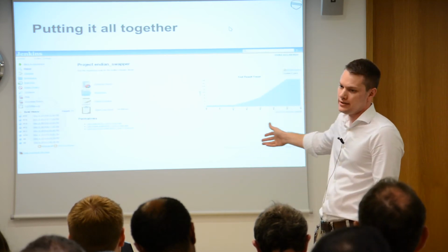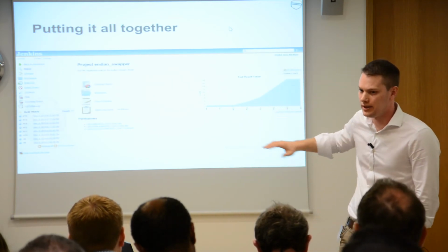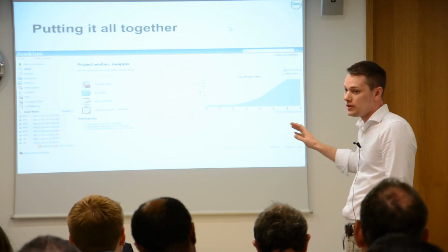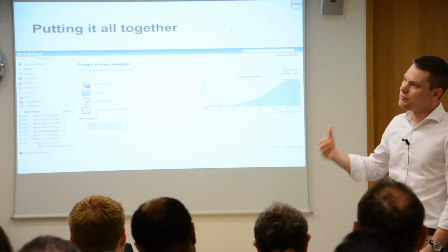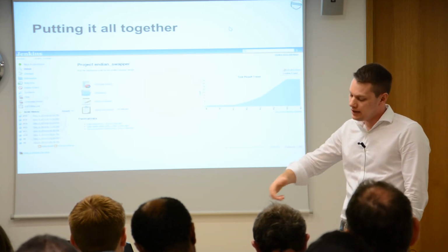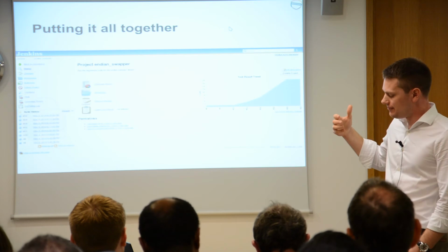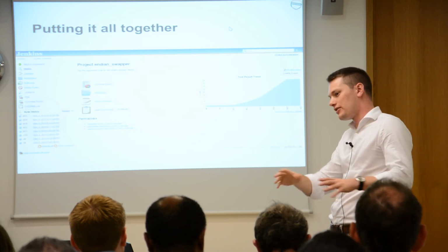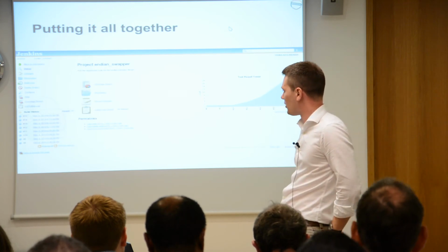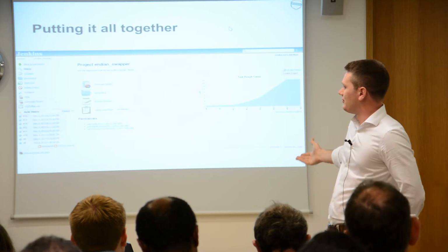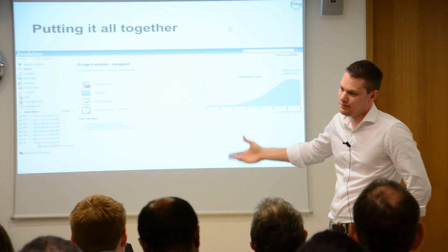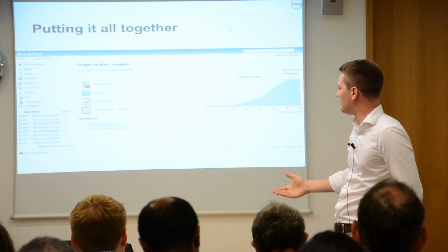You get nice test result trends, you've got a regression, it's triggered off a post-commit hook, everything works, and the test takes 30 seconds to run. What we found is you go into a company, and the majority of chip design companies are quite behind the times when it comes to continuous integration using open source tools. We've gone into places where they've got some hacky Perl system with hundreds of scripts that takes months of effort to maintain, and it's forever breaking. And we turn up and in an hour we can have a Jenkins setup up and running with a Cocotb test bench, effectively replicating what's taking them months of effort to achieve.